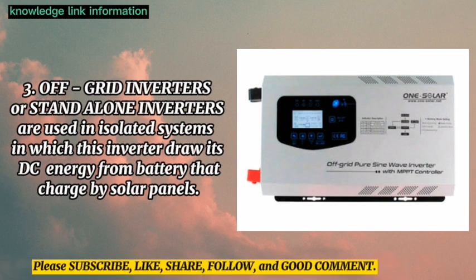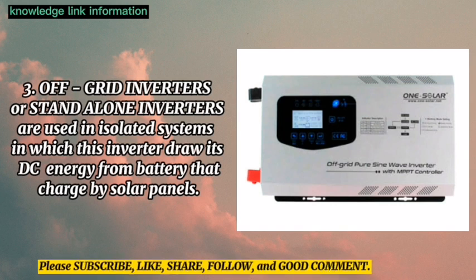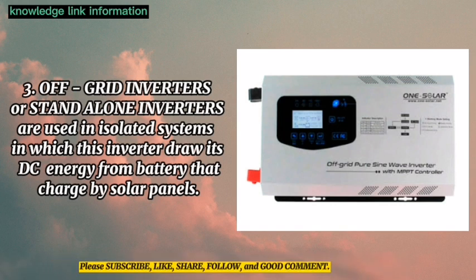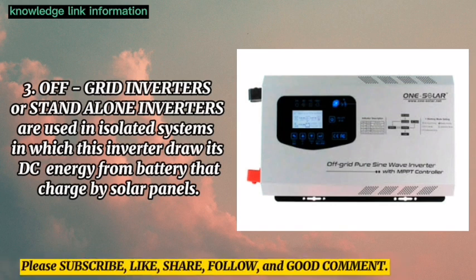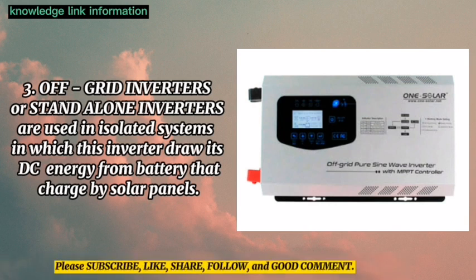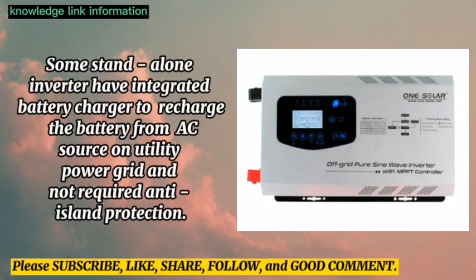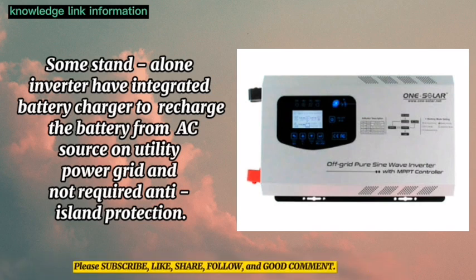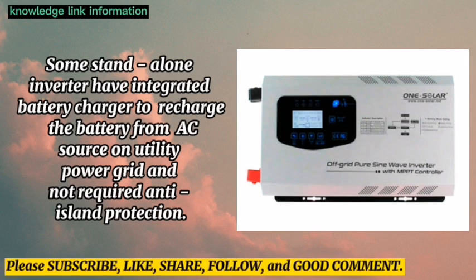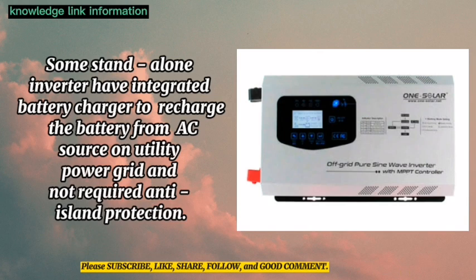Number 3. Off-grid inverters or stand-alone inverters are used in isolated systems in which the inverters draw their DC energy from batteries charged by solar panels. Some stand-alone inverters have an integrated battery charger to recharge the battery from an AC source on the utility power grid, and do not require anti-island protection.